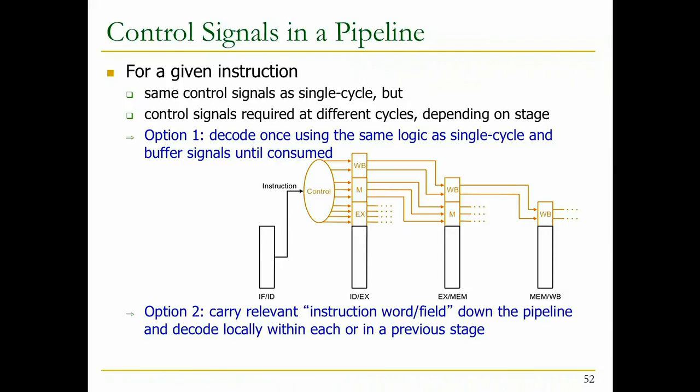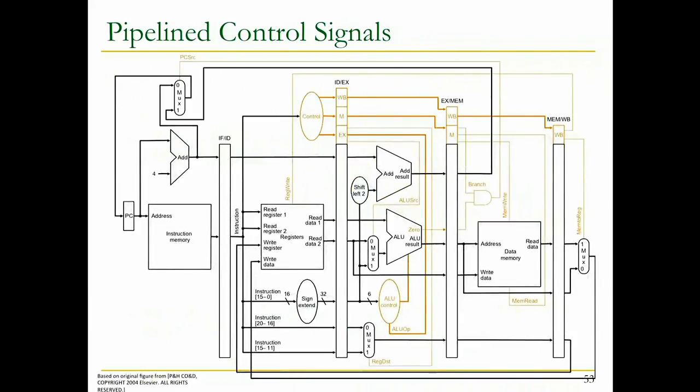That way you can get rid of the overhead of some of these registers a little bit, but now you add more combinational logic. Basically, you distribute your control logic or decoding across the stages, which may not be a bad option, actually, as long as you can do that. So which one's better? The answer is it depends. Basically, it depends on the design and what you're constrained with, right? Sometimes it may be better to generate the control signals than just propagate them. That sounds simple, right?